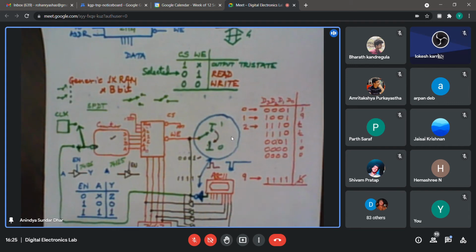Yeah, 125 has an active low enable, so you can use 74125. It contains 4 such buffers. Though I think it is coming as a single IC. But the control lines you need to connect. It has separate control lines for each of these buffers, so you need to connect all 4 together to make a common control line.